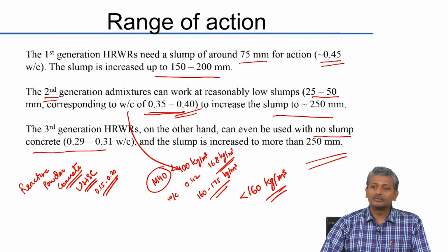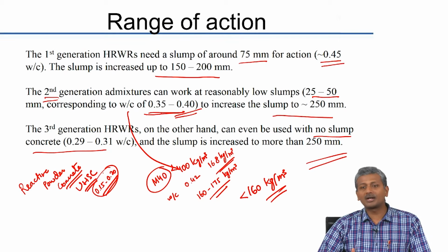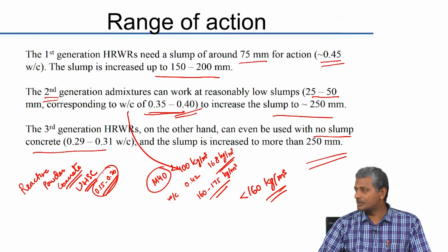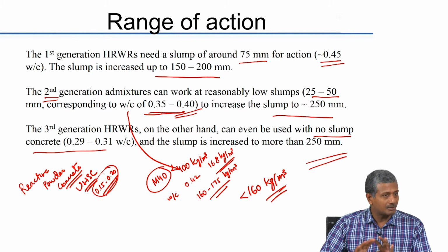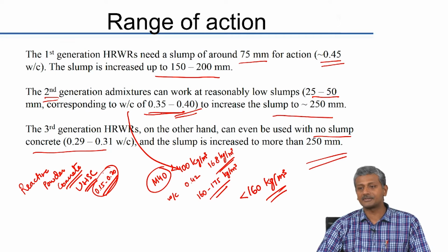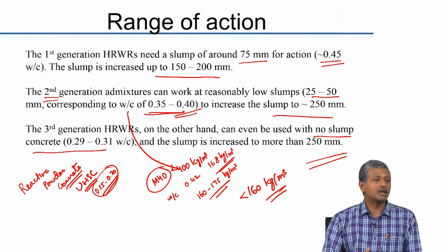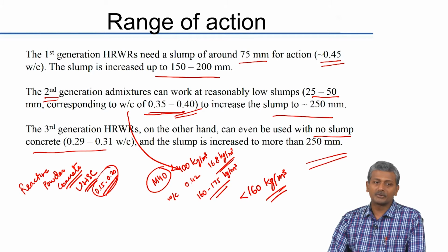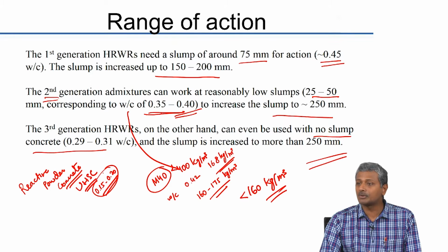Okay. So, here we are talking about water cement ratios which are so low that the water content in the mix itself is extremely low. So, when you are adding very high amounts of superplasticizer into this system, it will take a long while before this SP actually interacts with all the cement particles present in the system. That is why the mixing time has to be enhanced more and more as you are going to lower and lower water to cement ratios. So, in talking about 0.15 to 0.2 water cement ratio, mixing time is already enhanced to about 30 to 40 minutes.